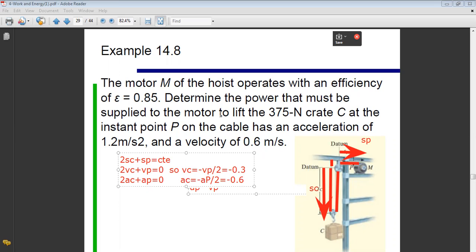To get the useful power, by definition, what is P useful, okay? What is the power useful here? What is my purpose in this problem? My purpose is to lift my crate, okay? So to do this, I should develop a certain tension in my cable, okay? And as we said, the definition of power is T dot V as vectors, okay? T dot V. And since here they are collinear, so it's the scalar product of tension and velocity.